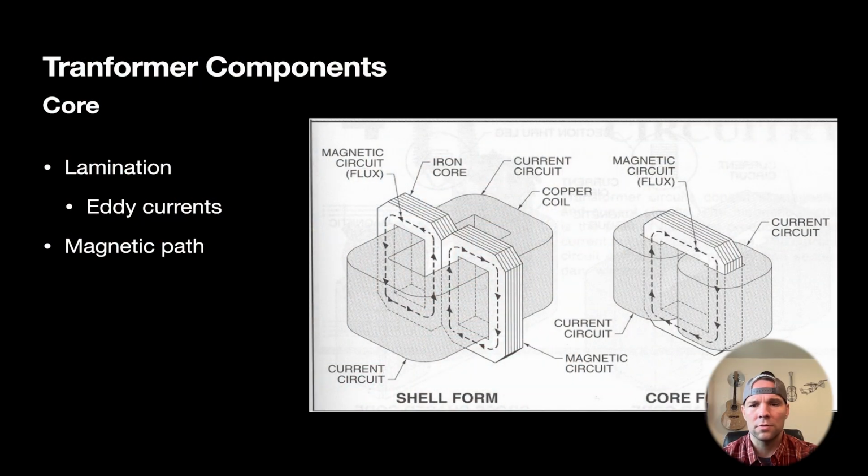So when we're talking larger transformers, such as distribution transformers, power transformers, all right, there's some typical components that come with the transformer. So the first, we have the core of the transformer. So the core is the iron core that the windings are wrapped around. And what that core does is it creates structure for the windings to hold them up. It also concentrates the magnetic field, so it makes it a little bit more efficient.